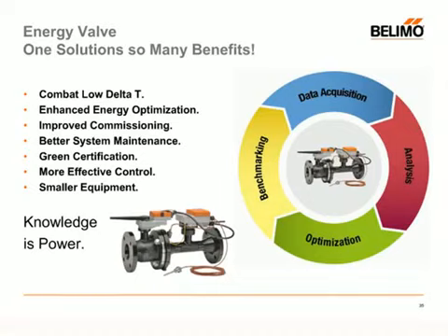As I mentioned before, you have a dramatically improved control system. One engineer that I presented this to, he described it as you're actually controlling on delta T instead of controlling on pressure and accepting delta T's that come off your units. You're actually controlling to delta T, and when you do that, you get pressures. So it's completely flipping the design. You're actually operating the equipment the way it's actually designed.